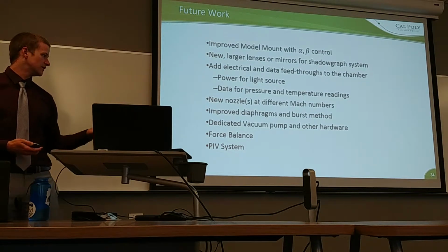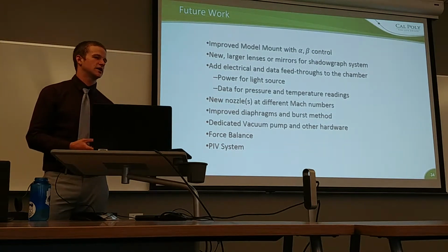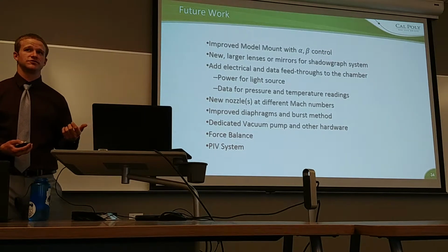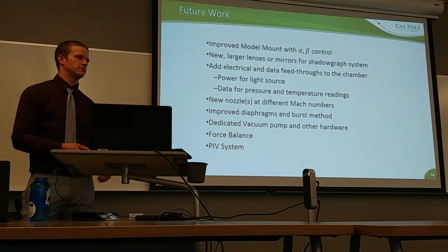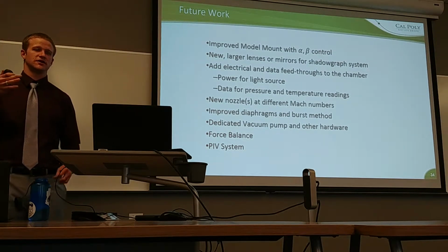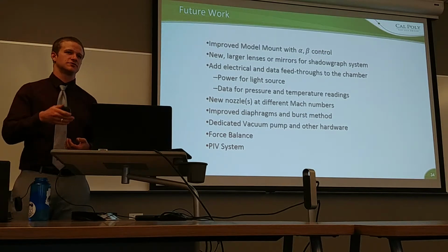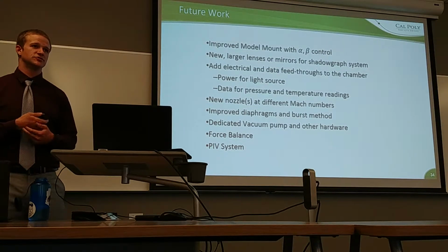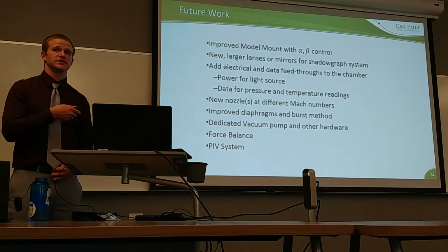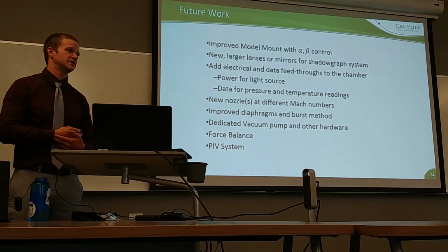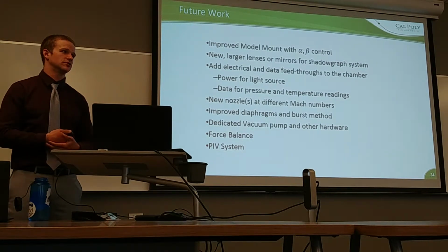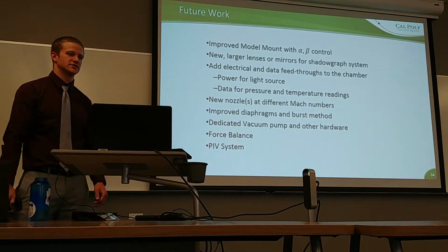And then particle image velocimetry can also be added. For supersonic flows it's typically very difficult to perform PIV because you need to seed the flow with small particles, which you then view with a camera after passing a laser through them. But supersonic flows are typically really difficult to seed. Because this chamber opens to the outside, it should be relatively easy to seed the flow, as you can just fill the area around the chamber with the seeded flow and it'll be drawn into the tunnel.